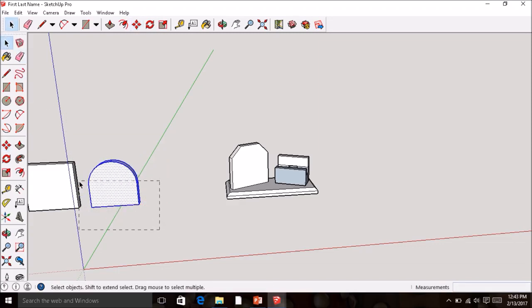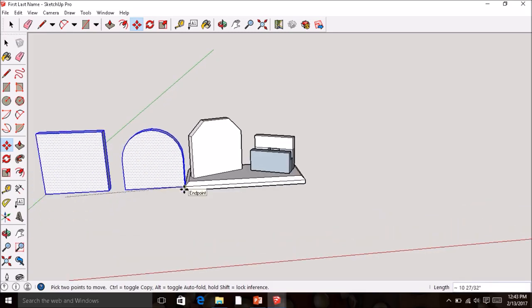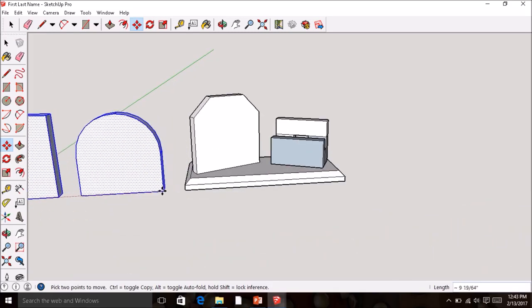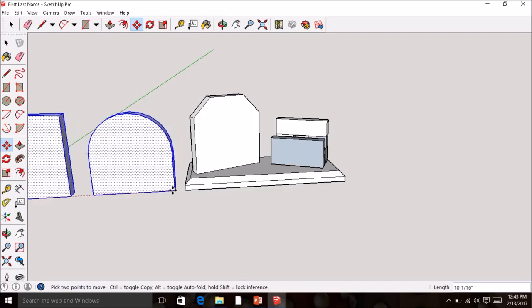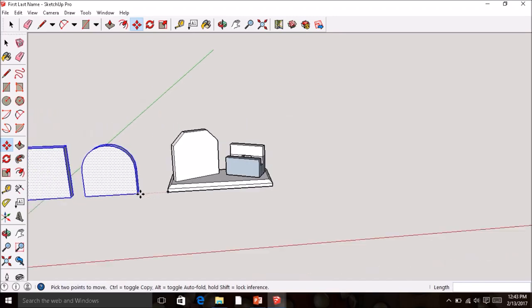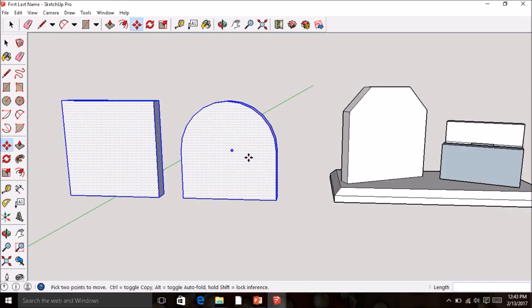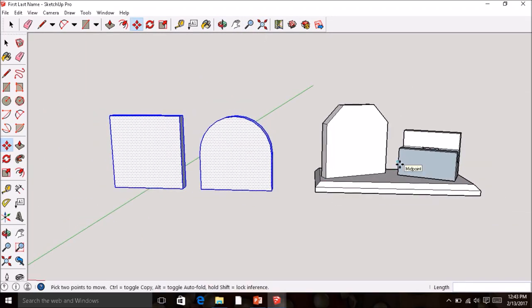I then can grab both of them, zoom out a little bit, grab them both. And I can move from this endpoint, come down to my clock to the endpoint, move it over a little bit on the red. Hopefully it will say the red. All right, so I know I'm fairly centered on the red axis. Right, and I could go zoom extents. That way I know you've drawn both, and then you've chosen how you want it set up.